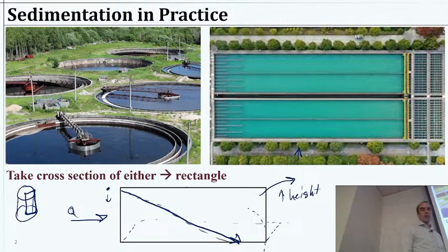If you've ever done anything around the area where the Mississippi meets the Gulf, you know there's a lot of sediment. And if you go far enough away from the Mississippi, you will have settled out all the settleable particles. And we're going to discuss why that happens today. And if you go way out into the open ocean, the water is much clearer than it is where the Mississippi is meeting it because of that difference in particles in the water. So the Mississippi River Basin and that whole estuary system can act like, or does act like, a massive sedimentation basin.